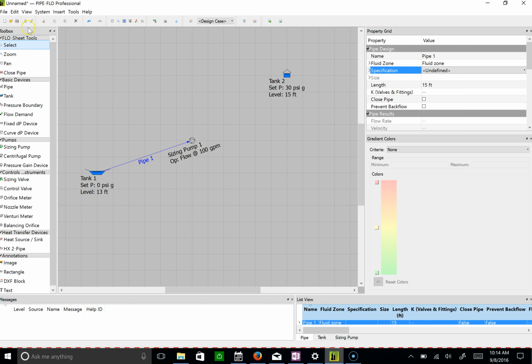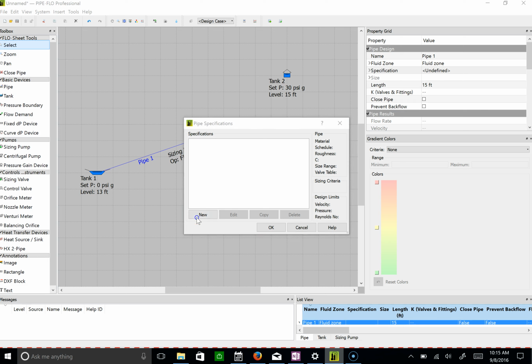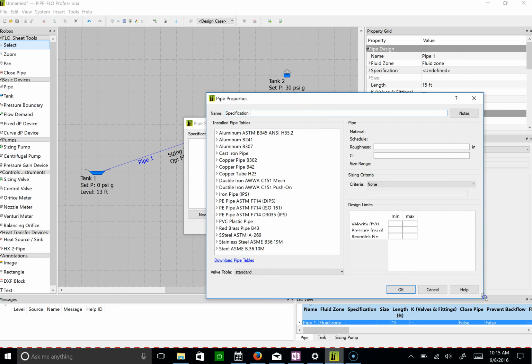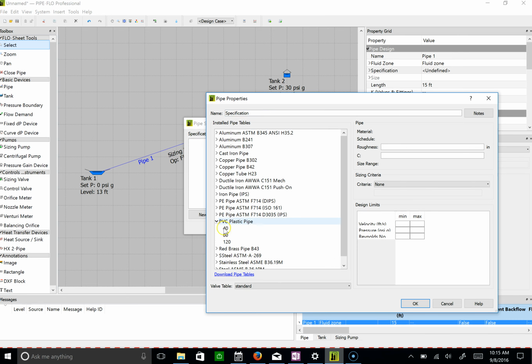Oh, yes, thank you. That is under systems. Yeah, let's check that. Let's click new. Ah, thank you. And I think we wanted what? Was it PVC? Schedule 40? I think that's what it says. Click, oh, sizing criteria, design velocity, put 8. All right. Now I think we're good. So if you click OK,